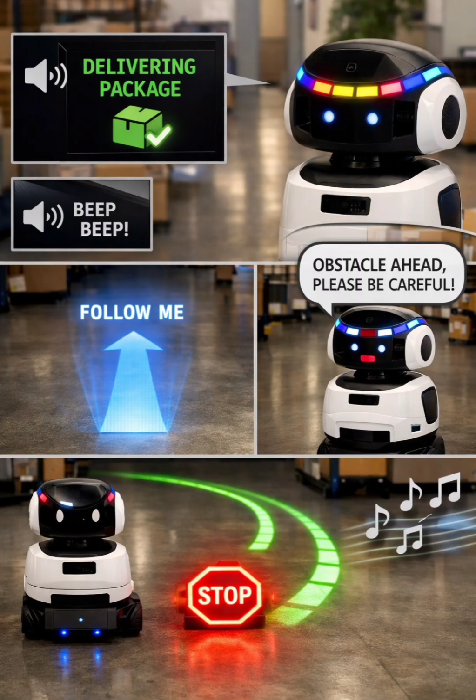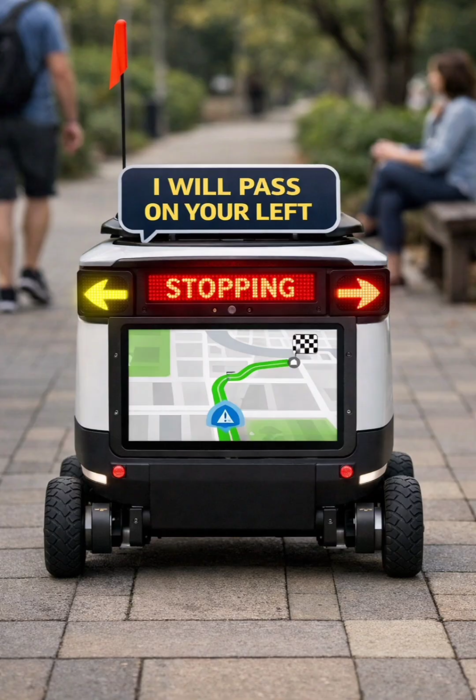Second, it provides output channels, so the robot communicates intent and status. This includes visual displays, lights, sounds, projected paths, or spoken messages. For example, a delivery robot can indicate "I will pass on your left," show its planned route on a screen, and signal when it is stopping or turning, which reduces surprise and improves safety.